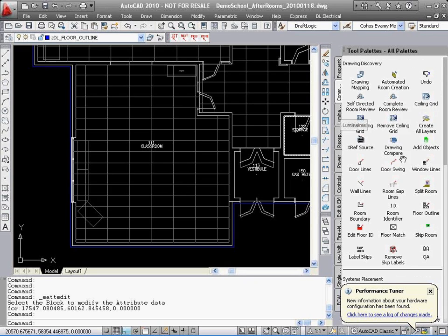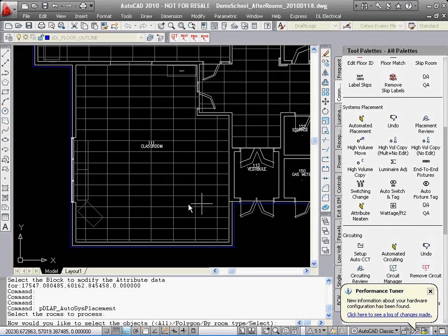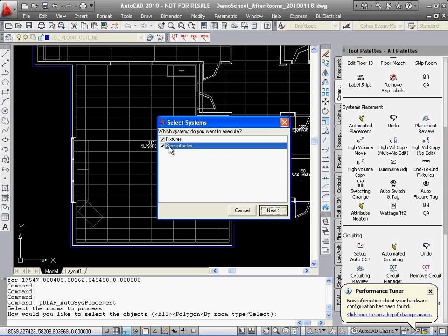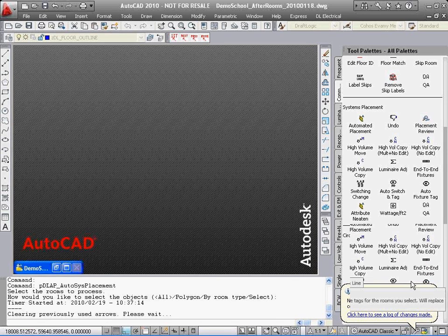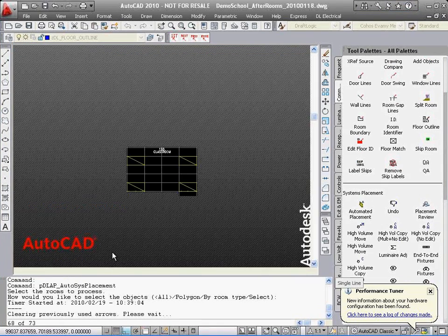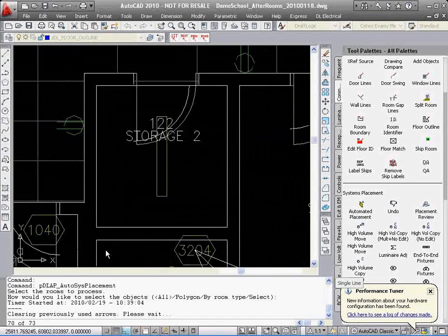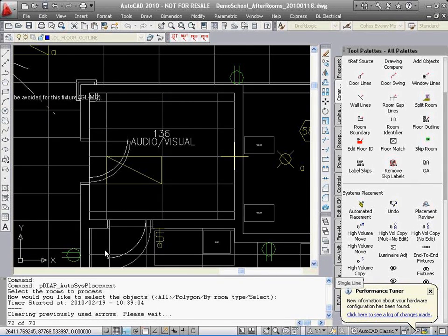The software will look for items that need power based on rules selected and place the appropriate device adjacent to that item, like a copier, microwave, etc. This is the time to locate motors and lay out other systems. The manual placement tools really help streamline this part of the design.